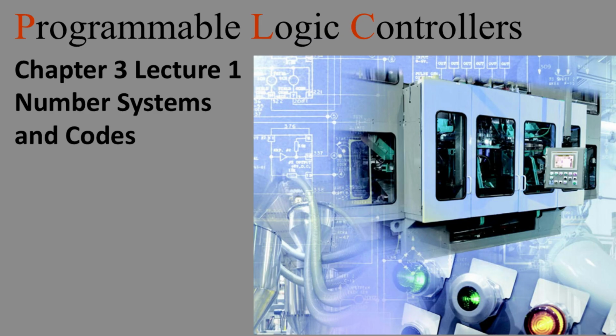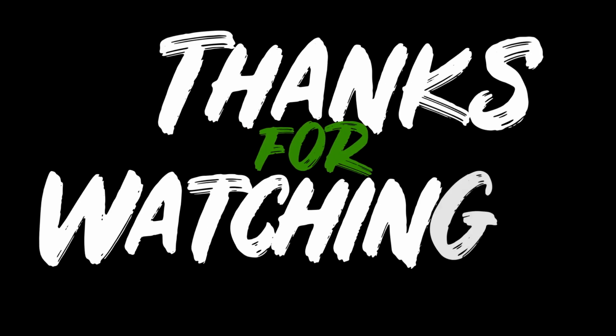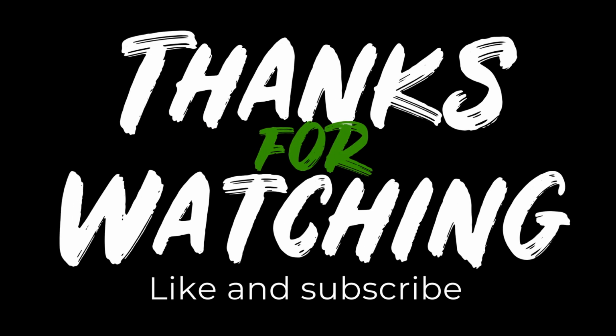In this lecture, we started with the decimal system, the base 10 numbering system that we use every day. We then moved into the binary system, and finally, we looked at the hexadecimal system. Together, these 3 systems form the essential language of digital logic and computer memory. In the next lecture, we will build on this foundation by looking at special coding systems, such as BCD and gray code, which are designed to solve specific practical problems in digital electronics and industrial control.